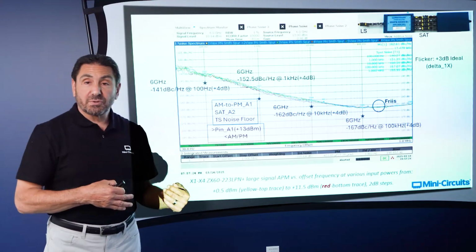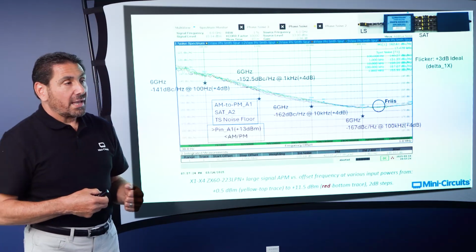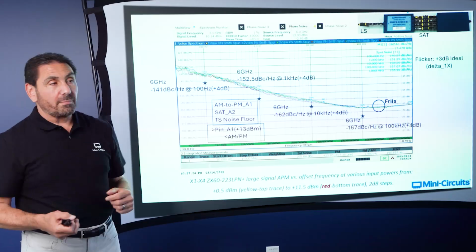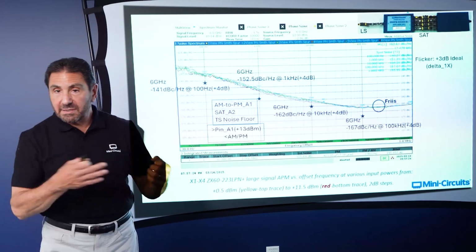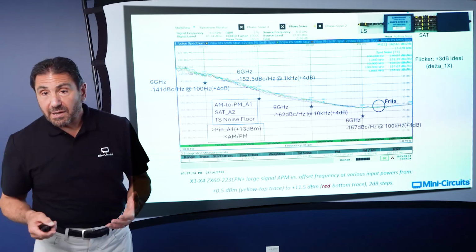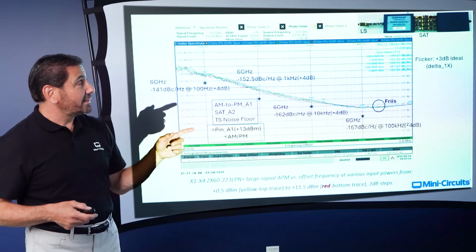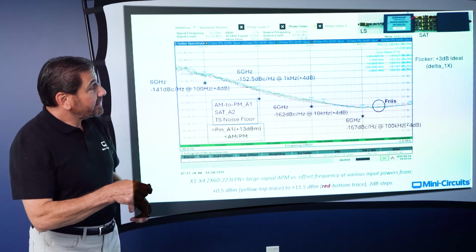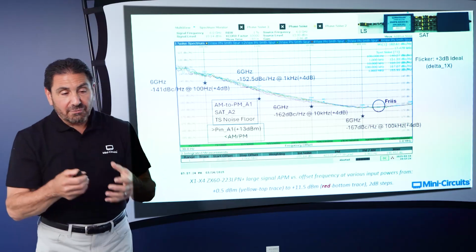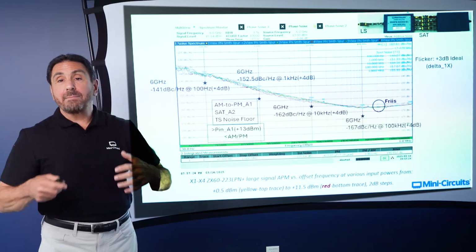Well, we can change the input power range. That's easy enough. And we can change the power level into the four parallel combined by using a pad, like we did in part 2. Are we going to get the same output power? We're going to be pretty close, because don't forget, we're saturating the heck out of this. So by pulling that out of saturation, like we did in part 2, replacing that loss with a pad, we're not changing the output power that much.